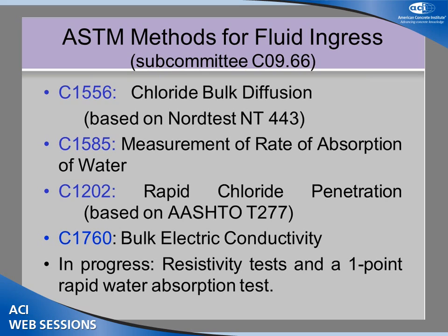some 10 or 15 years ago, I formed a subcommittee at ASTM on methods for measuring fluid ingress, subcommittee C09.66, and we've developed several standards, one of them being the C1556, which is a chloride bulk diffusion test based on the Scandinavian method, and C1585 on rate of absorption. We already had the C1202 rapid chloride permeability test, which predated the committee.